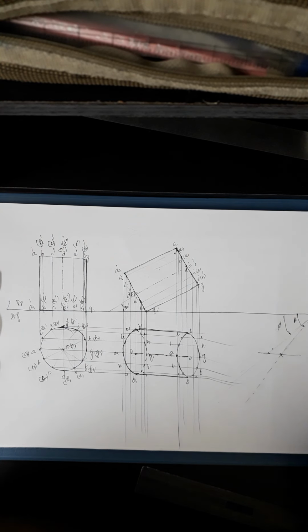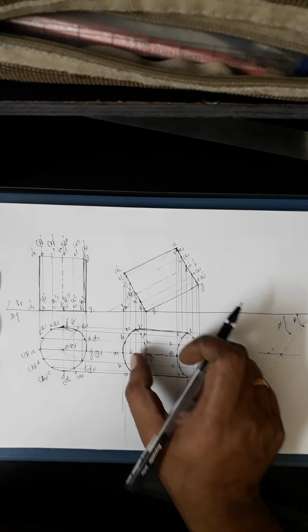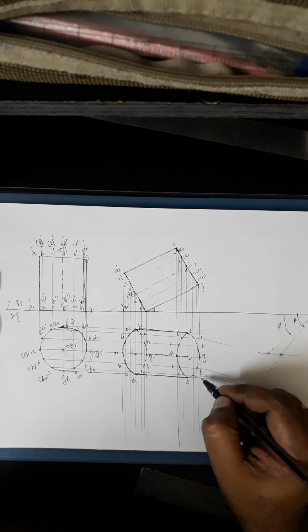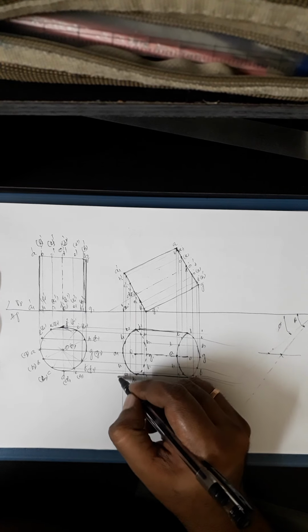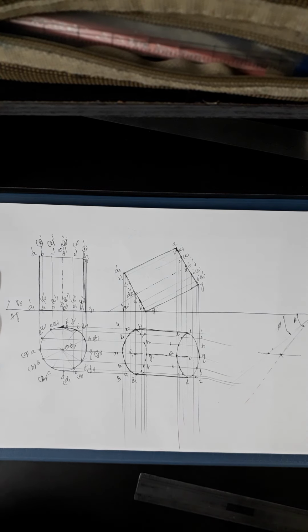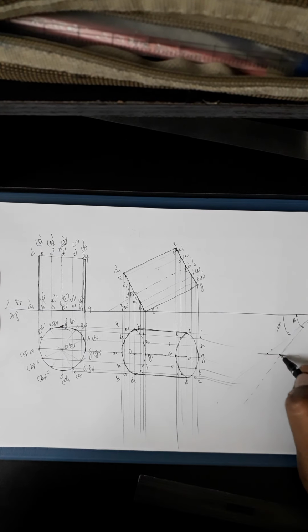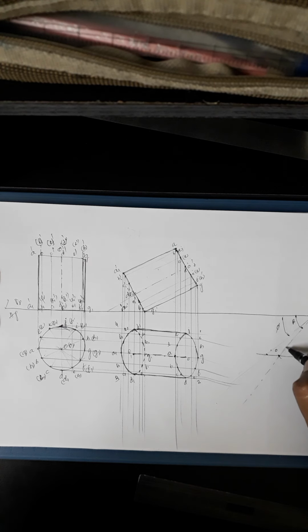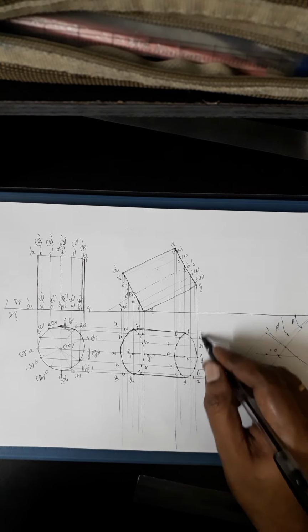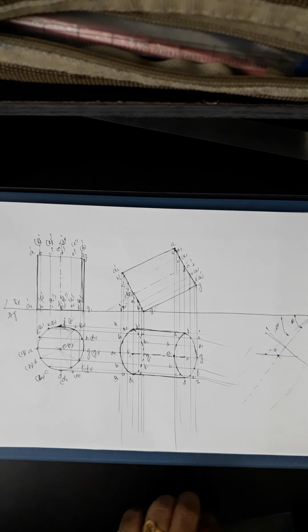You can take from any point, anywhere, this length, and redraw. To redraw this curve, you have to inscribe this in a rectangle. That will be better, because there are many points and you cannot locate all of them. Instead, let this be O, take O to G. I'll draw a line perpendicular to that to get this 1 and 2. Then parallel to this line, because beta is the inclination, we'll draw that rectangle 1, 2, 3, 4.